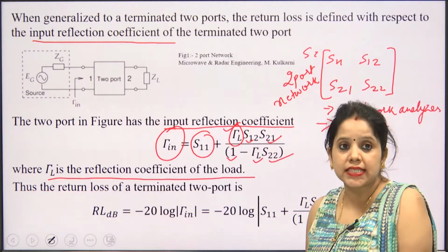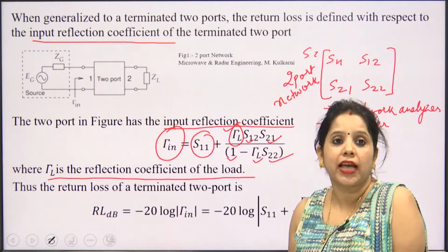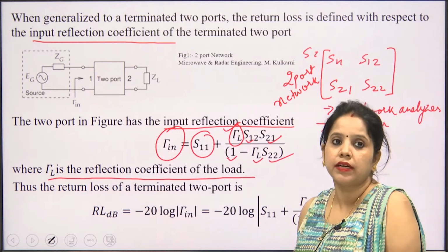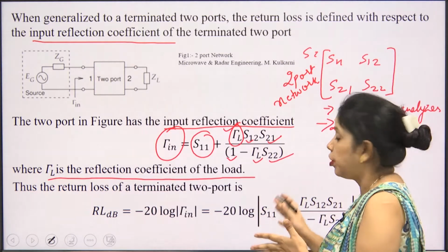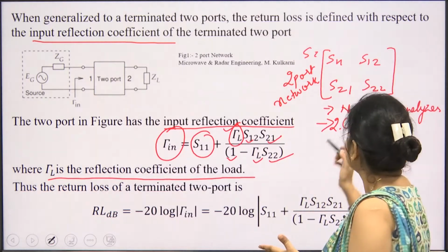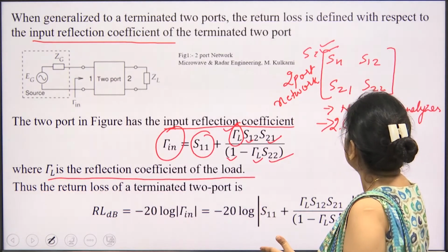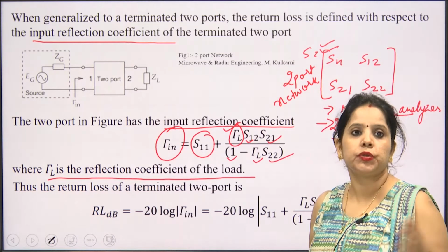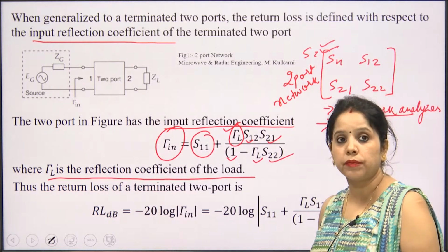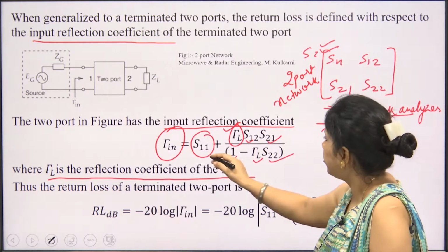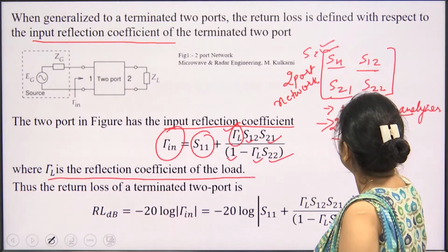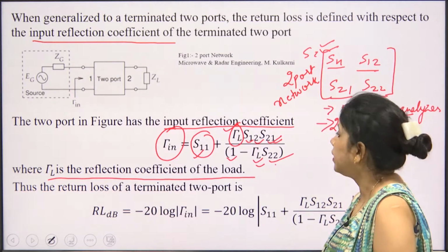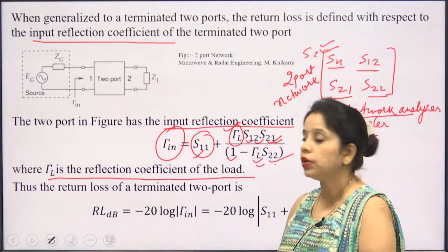We have already discussed this in our last lecture, where we calculated the scattering matrix of any microwave device. If we have our scattering matrix, which can be measured with the network analyzer and two couplers (you can refer to our previous lecture on microwave measurement), then we have S11, S12, S21 and S22, and we can apply them here and get the input reflection coefficient.